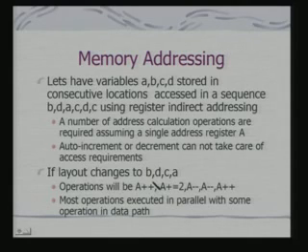So, if the layout now changes to BDCA, what is interesting is that I can do A plus plus, then I increment A by 2, fine, this is required, and then I can decrement and again I can increment. In fact, most of these address calculation operations are executed in parallel with some operation in the data path, because auto increment and auto decrement feature is part of your address generation unit.